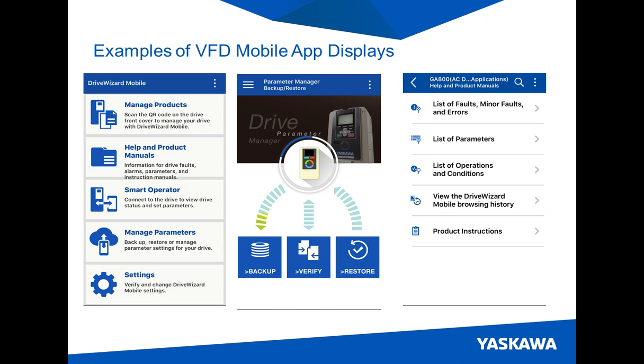Some of the other benefits is once you get a mobile app on your phone, you can leverage internet access or even cloud access to safely back up and store VFD settings. That's one of the screenshots that I've provided here as a sample of that. And the other benefit is the mobile device has wireless or Bluetooth technology built right into it. And that has many benefits that we're going to talk about for accessibility and safety.